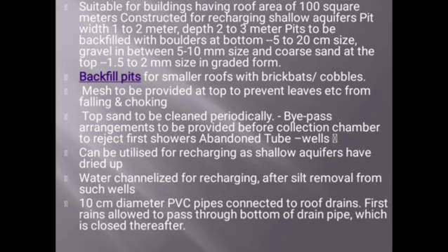Suitable for buildings having a roof area of 100 square meters. Constructed for recharging shallow aquifers, the pit is backfilled with boulders at the bottom of 5 to 20 centimeter size, gravel in between of 5 to 10 mm size, and coarse sand at the top of 1.5 to 2 mm size in graded form. Next one, backfill pits for smaller roofs with brickbats and cobbles. Mesh to be provided at the top to prevent leaves etc. from falling and choking. Top sand to be cleaned periodically.